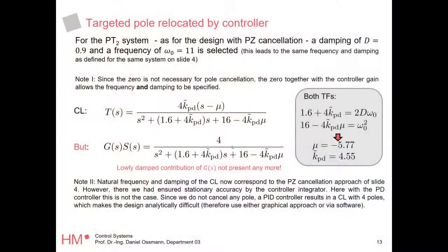And here I'm showing you now the new disturbance sensitivity with a PD controller. And you should see now, if you plug in the numbers here, that we actually moved these 2 poles and did not cancel them, right? So now we actively moved these lowly damped poles to a region where they are very well damped instead of canceling them and introducing new ones, right? This was the thing we did with the cancellation part last in the morning.